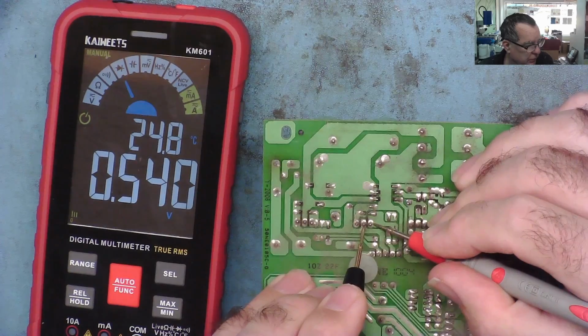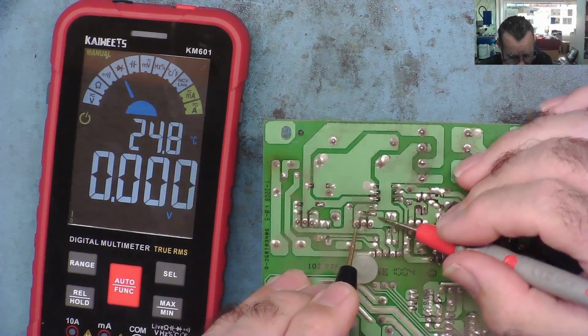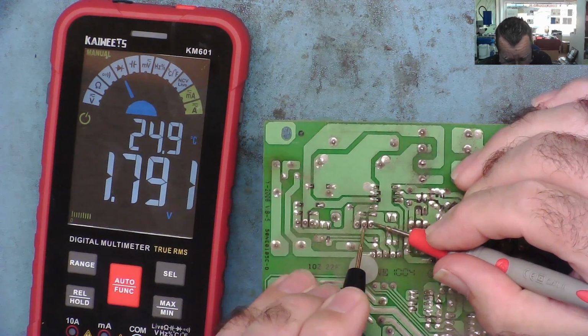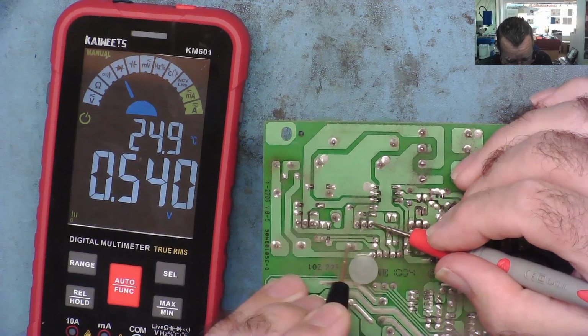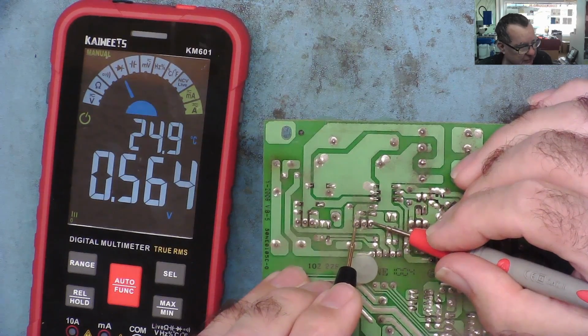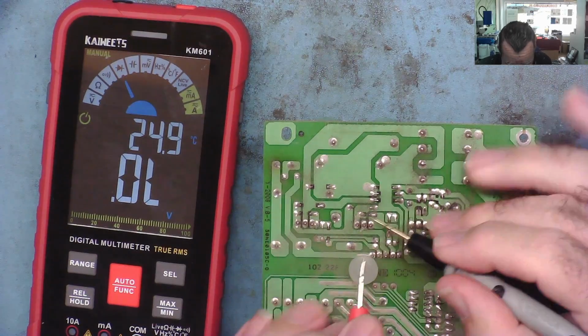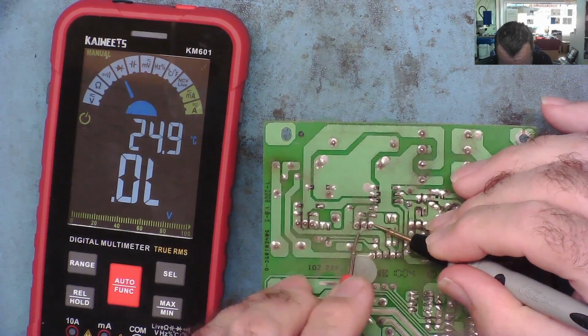Well, there's a semiconductor junction there, okay. And there's one there, so this is looking like it's the base. And these looking like the collector's normally in the middle on this type of transistor. But we can try the voltage method. 540, 564. That's the emitter, the higher voltage. What happens if we go the other way? Nothing, that's fine, there's nothing.